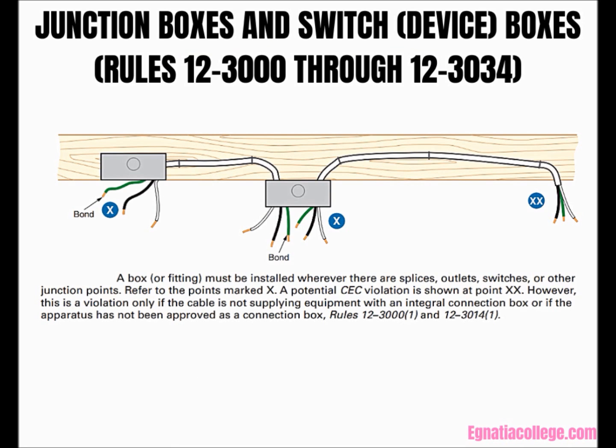Junction boxes are sometimes placed in a circuit for convenience in joining two or more cables or conduits. All conductors entering a junction box are joined to other conductors entering the same box to form proper connections so that the circuit will operate in its intended manner. All electrical installations must conform to the CEC standards requiring that junction boxes be installed so that the wiring contained in them shall be accessible without removing any part of the building.